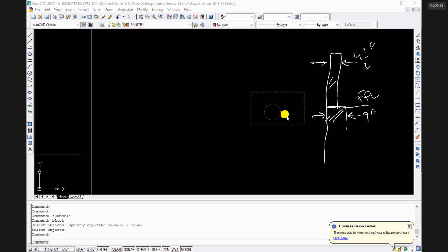When you go below, this is the property limit on this side. So your foundation would be on one side. This addition previously was 2.25, now it would be 4.5 inches. Right? And under this, you would provide a PCC layer.